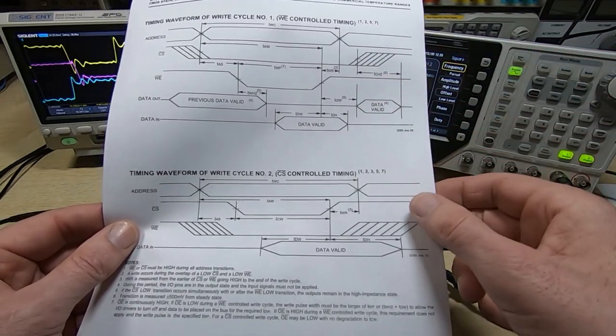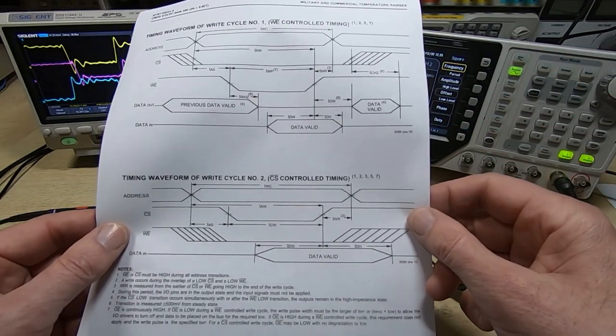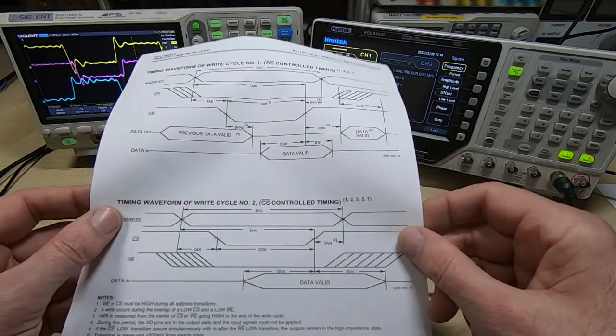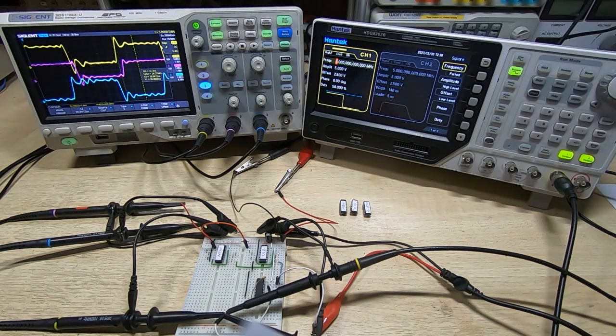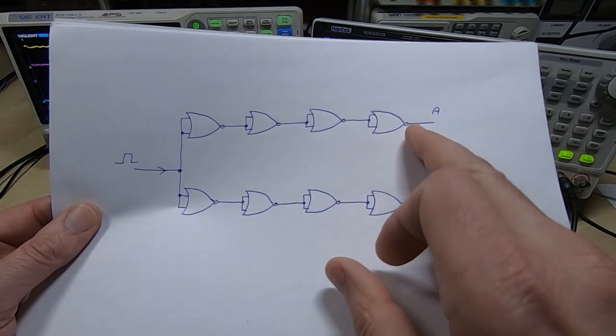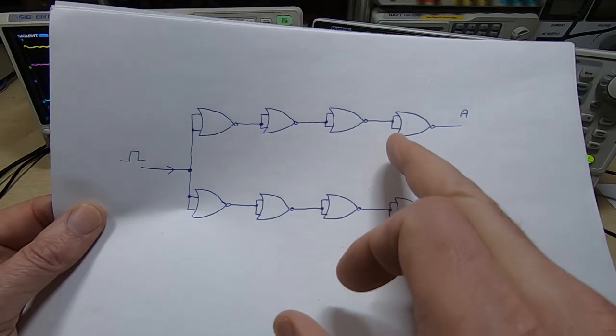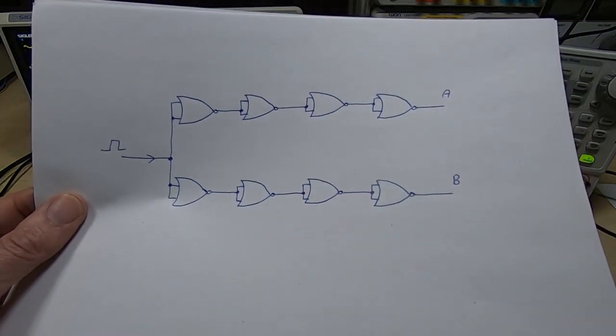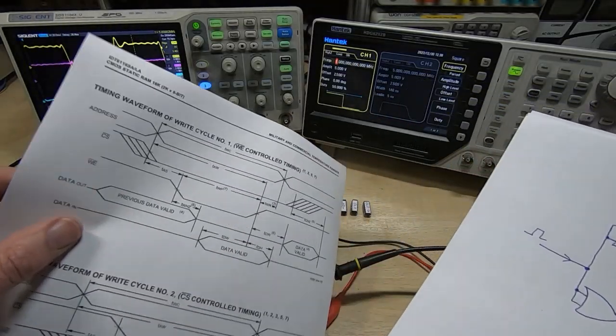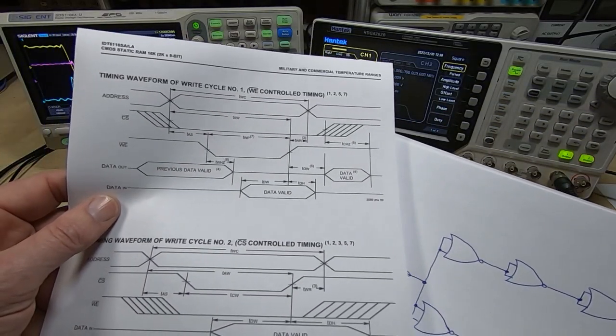Do that for all the major devices on the board, and you should fairly easily track down what's causing the issue, and all you've got to do then is work your way back through the string of gates that are feeding the signal, and at some point you should find the culprit, replace it, and hopefully that's going to be one step closer to getting your machine working.